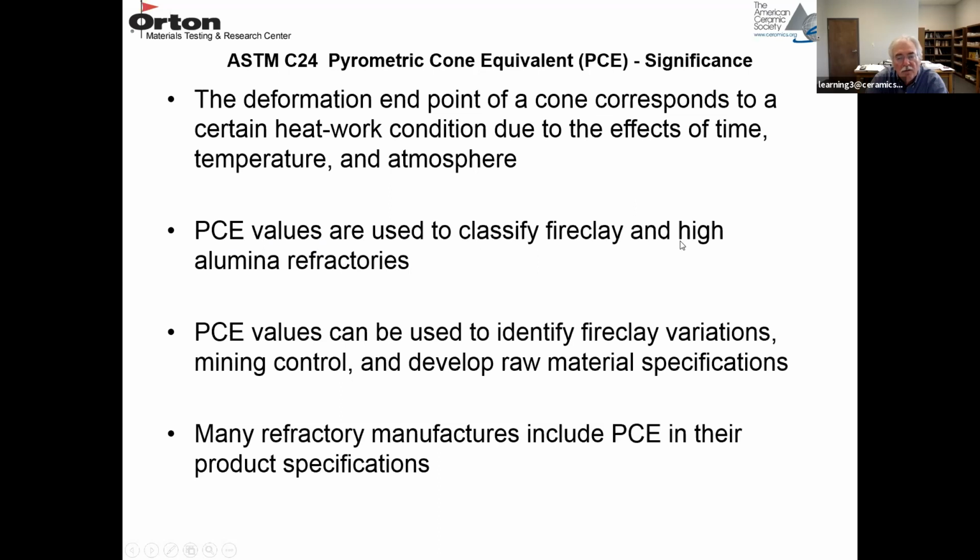PCE values classify fire clay and high alumina refractories. We just saw a table where there's a minimum value for each type of fire clay or high alumina refractory. PCE values can be used to identify variations in fire clay, mining control, and raw material specifications. So it's a quality control measure. You can use it at a clay mine. You can use it after you make a fire clay refractory. Most of the alumina silica refractories in their data sheets will have the PCE value. So it's a product specification.